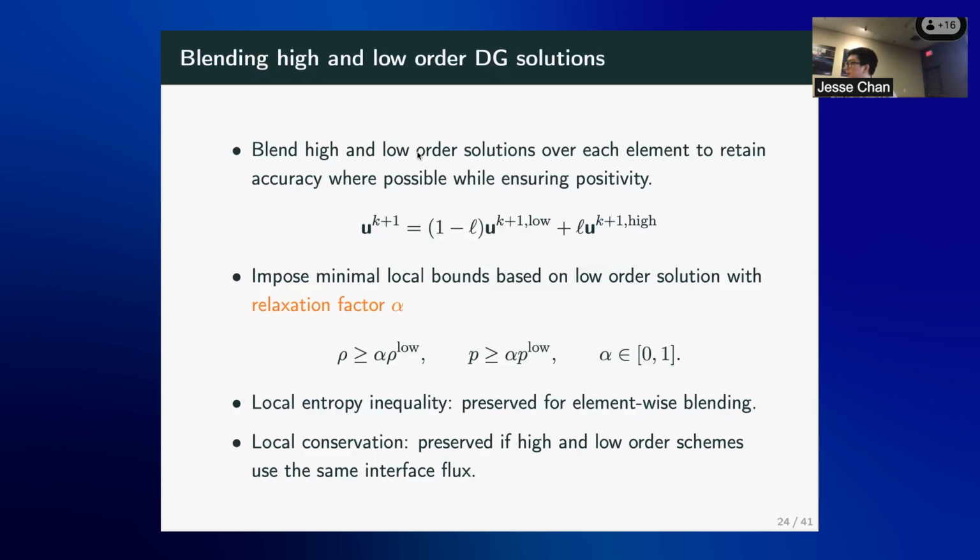So you basically just put a little slop in or something like that? Well, we choose that using alpha, setting alpha to be something like 0.1. It's relative. Yeah, that has proved to be really important for us. When we first tried this using Zhang and Shu's limiter, it's tough. I think it works well if you... I'm not sure how they do it. I think they have some TVD limiter on top of it, but for us, we just saw that the time step always converges to zero.